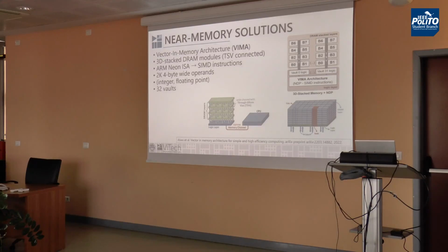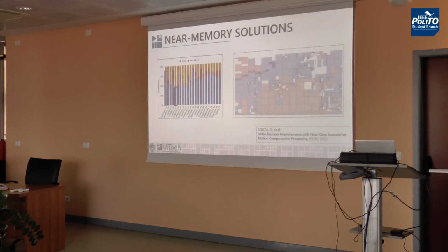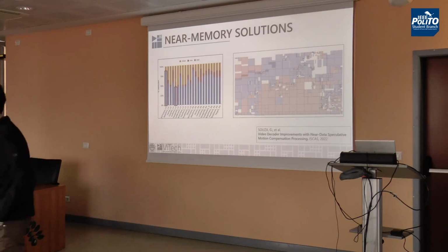Doing that works very well in scenarios where the cache memory cannot handle. If your cache is working really nice for that application, don't even try this one, because you are bringing data once and then it's doing its job. So that's why we use the decoder side, especially at the motion compensation, because usually you need to copy a part of a block from a previous frame and you are never copying it again. So your cache is not working. You're just bringing data and you're using it once. It's the worst case scenario for your cache memory.